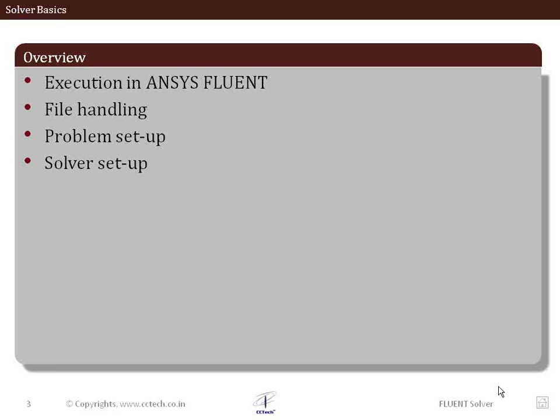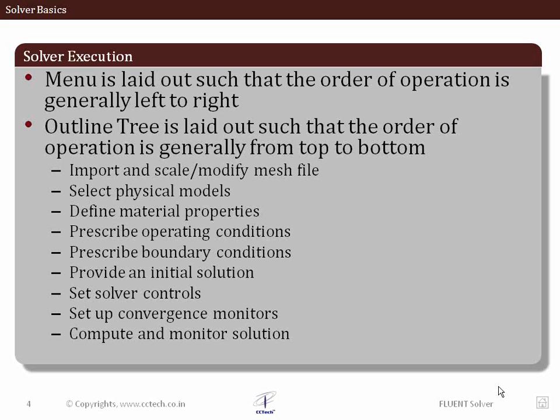Now the solver setup includes usually things like the numerical schemes, how the finite volume method, which is at the background of ANSYS Fluent, which it is using to solve the given equations that are defined in the problem setup, how they have to be solved, what are the different numbers, different inputs which are necessary for things like under relaxation factors or Courant number. So this very much depends upon the solver. So we're going to have a look at them one by one.